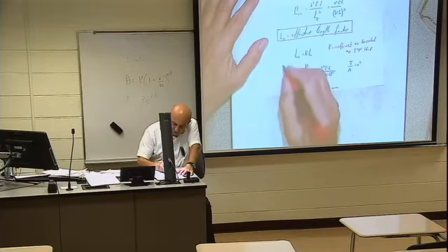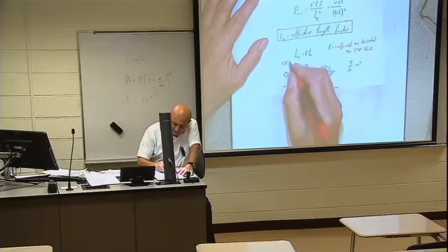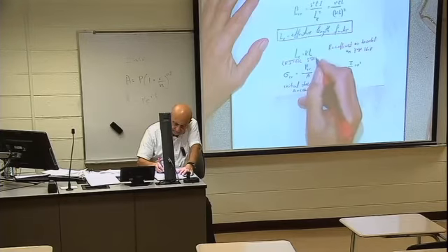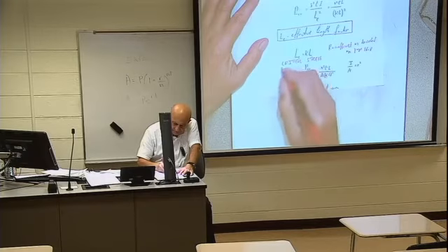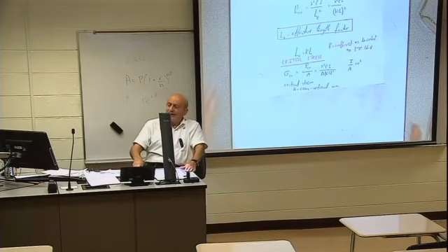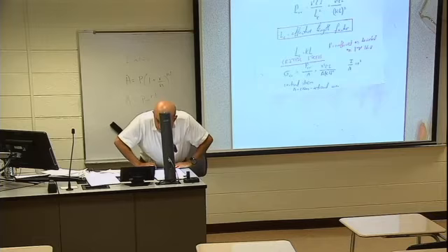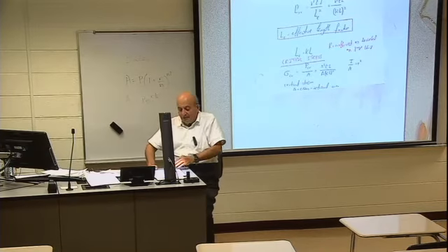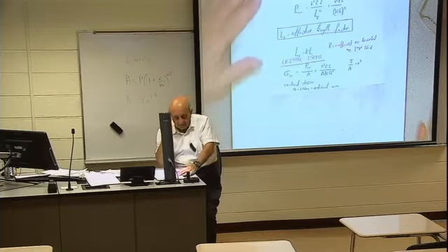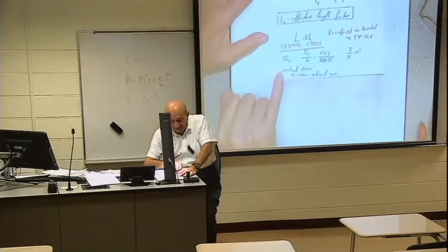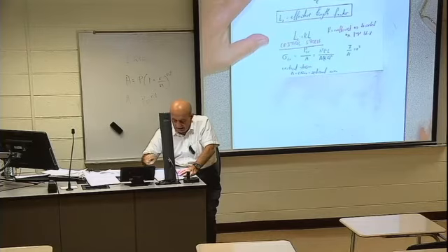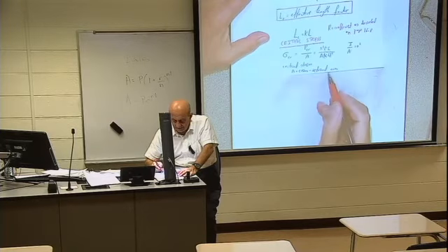Okay, now we would like to hear a new notion, critical stress. So what is the value of the stress? That is a question. What is the value of the stress during buckling? So sigma critical equals P critical divided by area. A is the cross-sectional area.